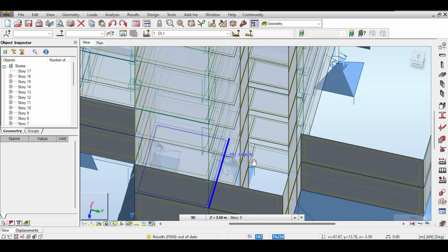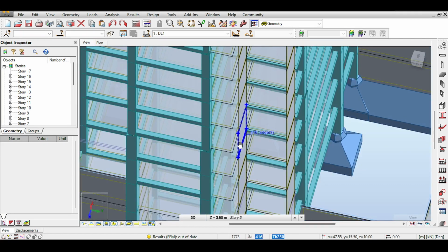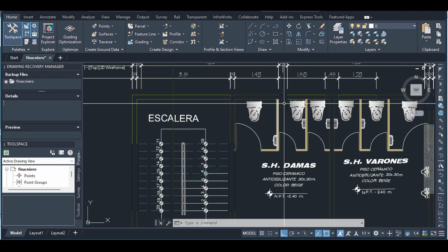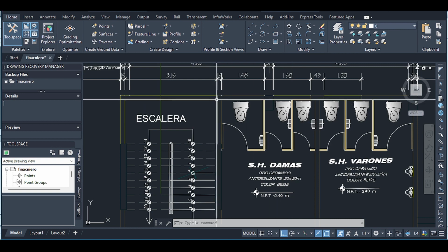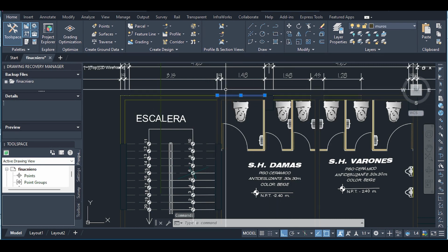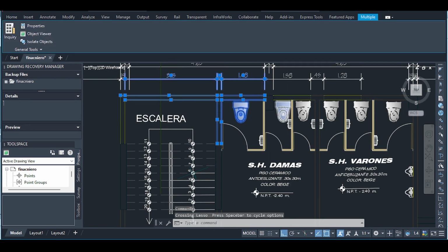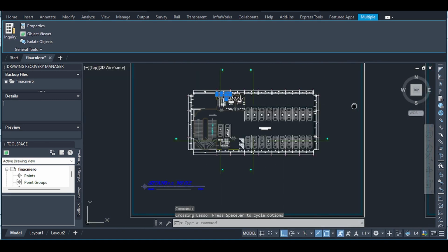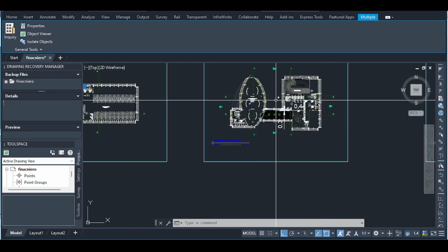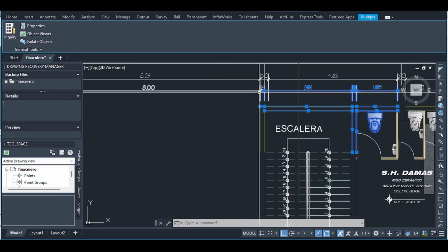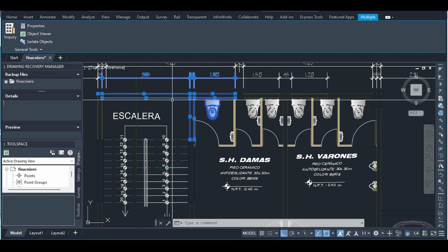Now those two columns are really close. Can I just make one column? I'm thinking now. This column, oh, this even looks misplaced. Look at that, this is just in the middle of the toilet. I think it makes more sense being here. So can I do it here? I need to check the other floors. I mean, here there is no problem. I don't need to check the other floors because it's at the staircase, for the love of God. So it's very easy to move it here.